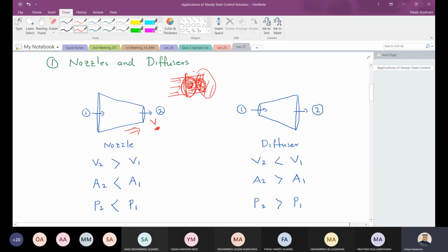Now imagine that you start opening your fingers slowly and open just a small space. What happens to the flow? It will jump. This high pressure starts pushing the flow, and from the small area the velocity increases greatly. The high pressure pushes the fluid at a high velocity at the exit, after your fingers, and this is exactly what the nozzle does.